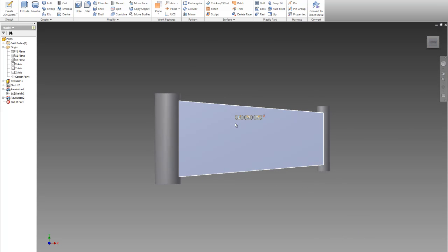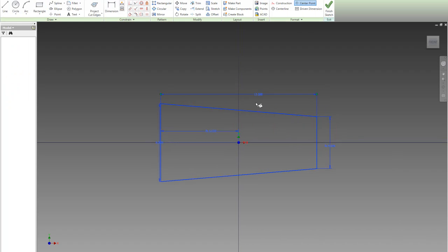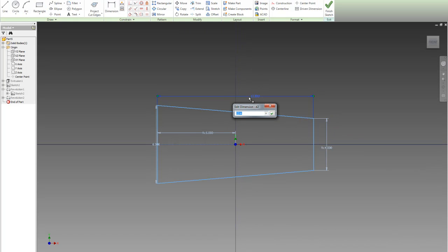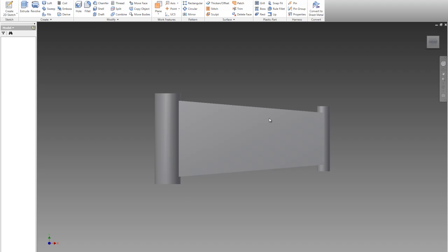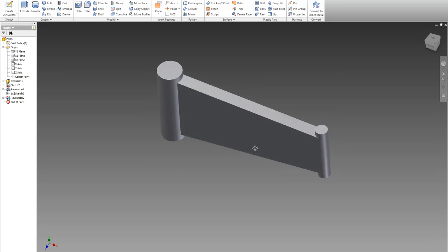Now when I select a surface, you can see glyphs appear again, which allow me to make changes, add a new sketch. In this case, I just would like to make a change. Again, going to that design with dimensions built off each other, notice how that properly keeps it centered because I had one dimension based off another one.